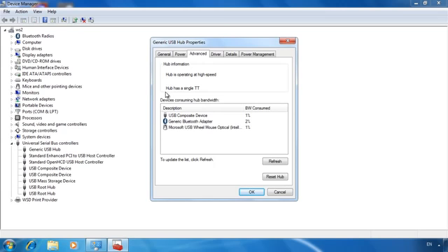When you plug a USB 1 device into a USB 2 hub, the device must change that single port from USB 1 to USB 2. The TT performs this. Without a TT, the whole hub must switch down to USB 1. This USB hub has 8 ports. Even with only one TT, I can still plug as many USB 1 devices as I like into the hub.